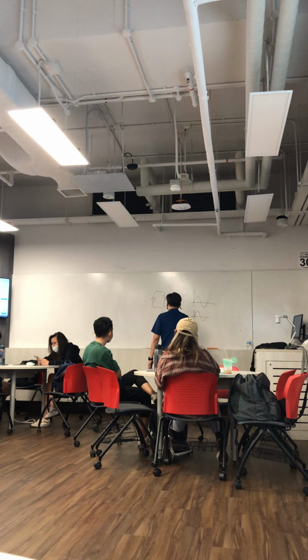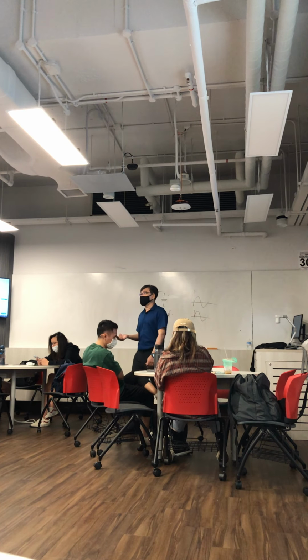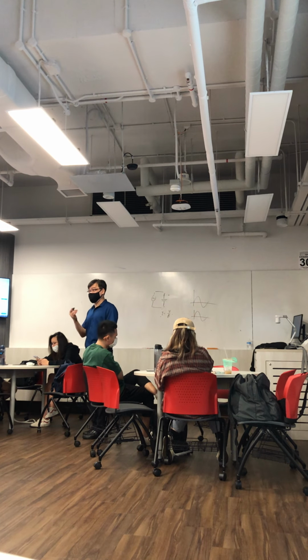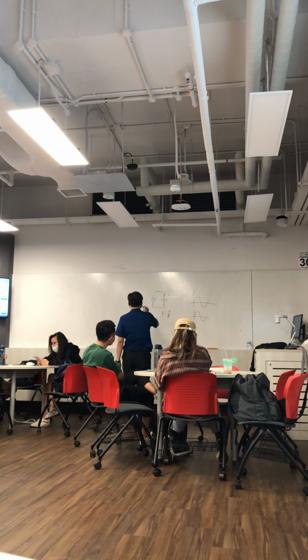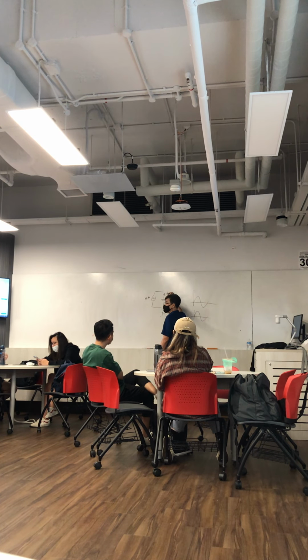But if I put in a capacitor, not so simple, right? Because the current becomes the integration of the voltage with respect to time. If this is not time changing, fine, but if it changes in time, what is the current here?